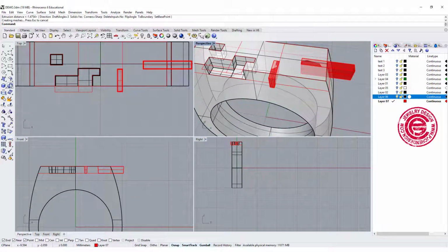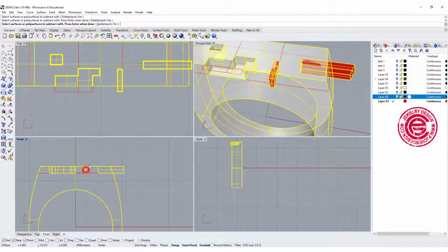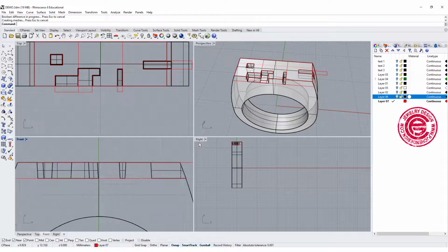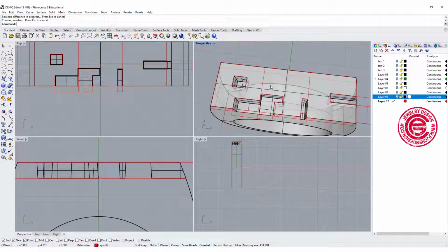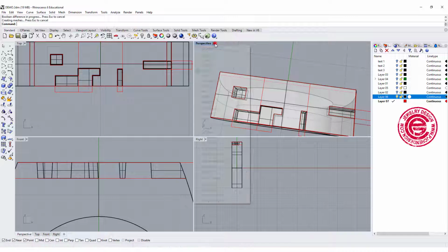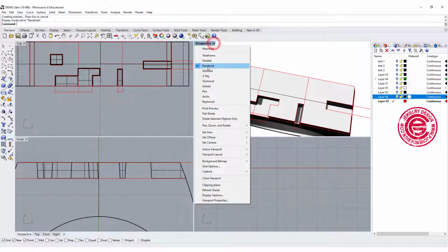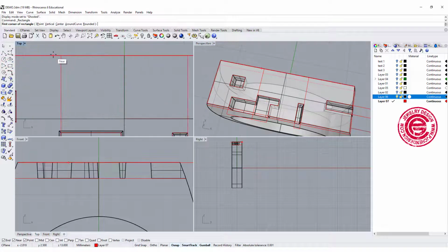Okay, and then let's do Boolean difference, this out of this and this. All right, so now we have things like this. We are ready to go. However, somewhere in the middle, it still sticks together if you take a look on the render view. So I do need to have a small cut right there as well. So let's go back to the ghost. We just need a small cut from there.